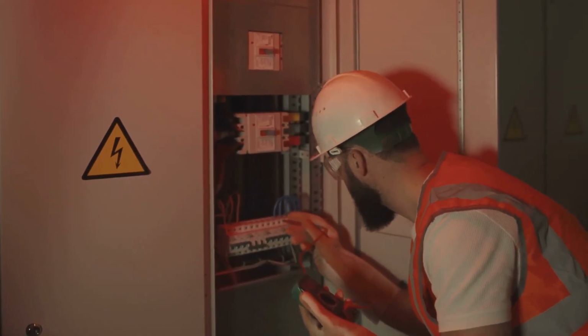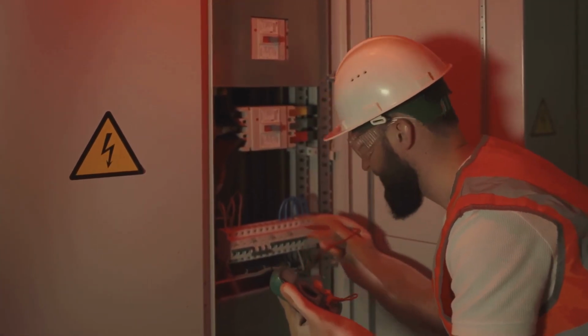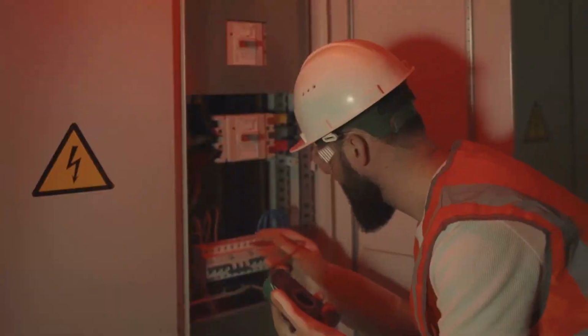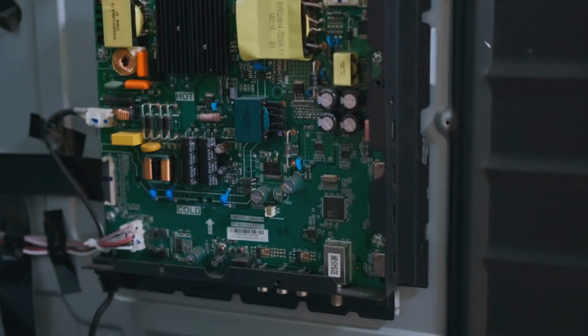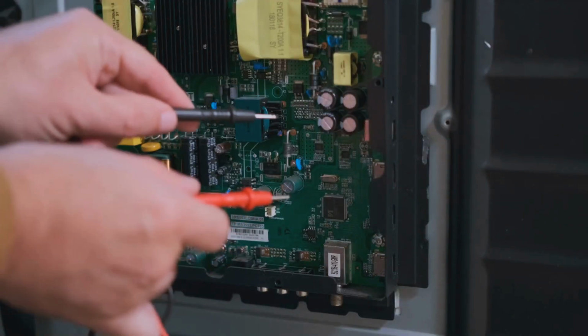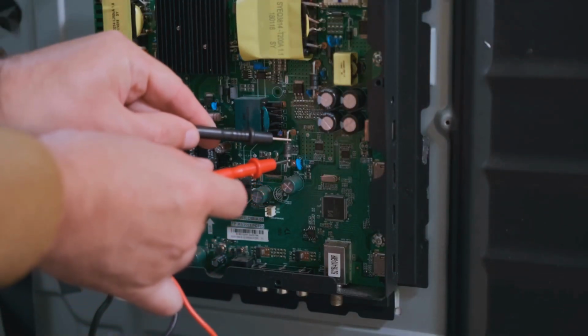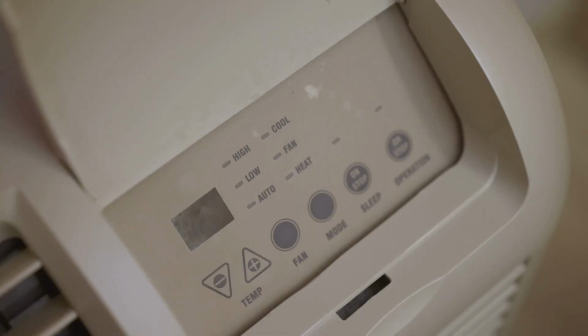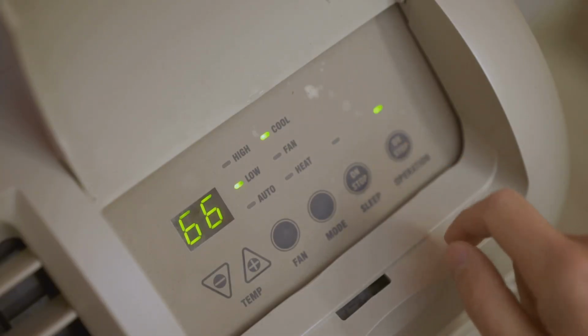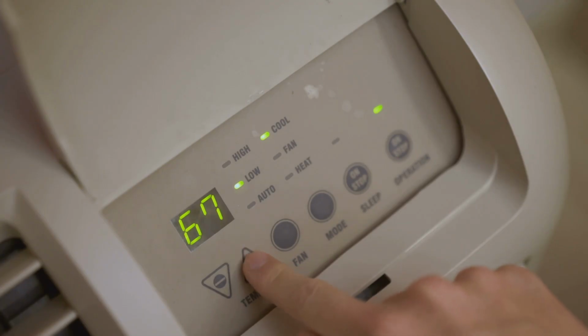Section 5. When a heat kit needs replacement. A heat kit may require replacement when certain failures occur: when an element is burned or broken, when a sequencer stops staging correctly, when the high limit trips repeatedly, when heat becomes inconsistent or unreliable, or when heat damage is visible inside the air handler.